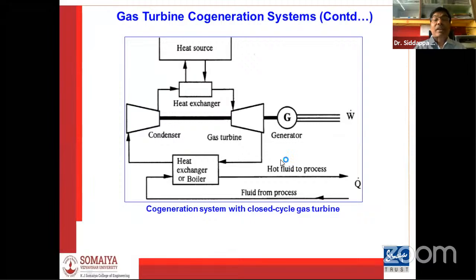Sometimes, for example in aircraft air refrigeration and other things, we are using a closed cycle gas turbine, but in a smaller capacity. To avoid some operating problems, we sacrifice the power there. And in that case also, air is sometimes used in the closed system, but it's not regular practice.